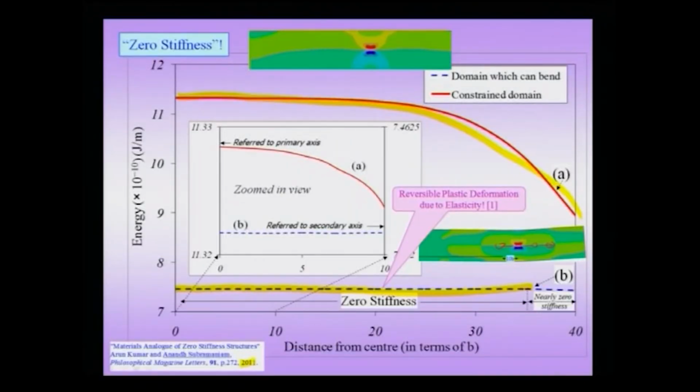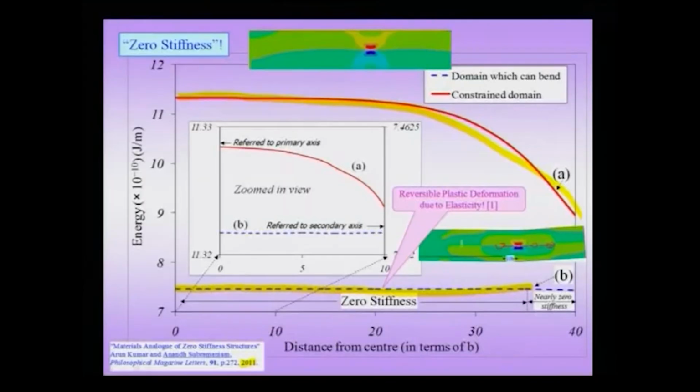Therefore, you can see that there are important effects coming from the presence of dislocations in nanocrystals. That means, in bulk crystals dislocations have certain characteristics. When you go down to nanocrystals, there are additional effects which come in and have to be taken into account, and a few of these we have already pointed out, like the image force, the domain bending, and the very interesting case, for a given specific geometry, of what you might call neutral equilibrium. And even more interestingly, suppose I now move the dislocation along the slip plane, which is now my central plane.